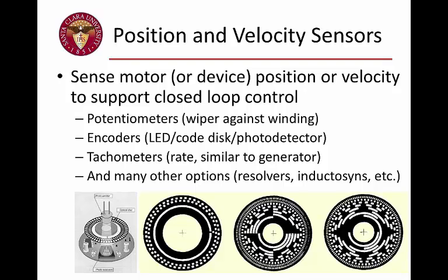Three of those optical masks are shown there to the right. The first one on the left would be used for direction of travel and speed sensing. And then the two on the right would be used for position sensing. And the two on the right, very interesting arrangements, almost artistic in some way. Those are actually two different kinds of binary patterns. The mask in the very middle is a standard binary pattern. So that geometrically reflects the way we would count in binary using normal binary code.